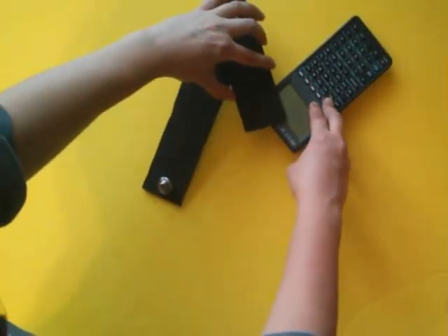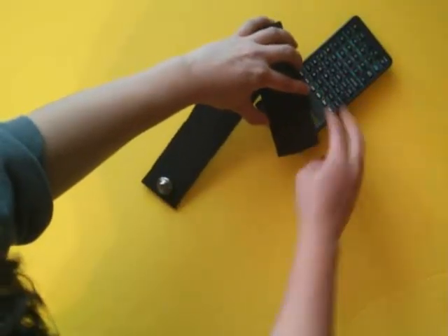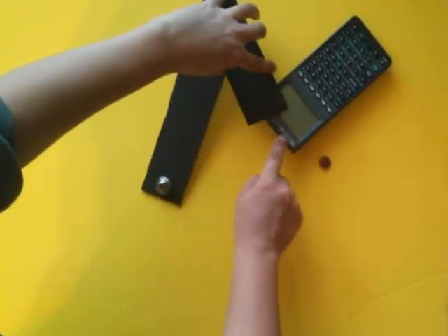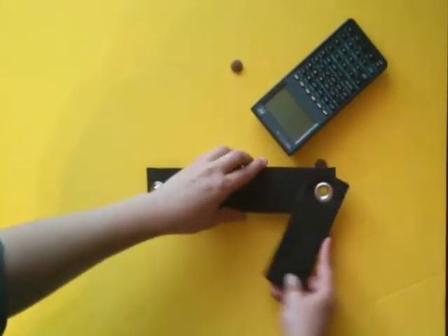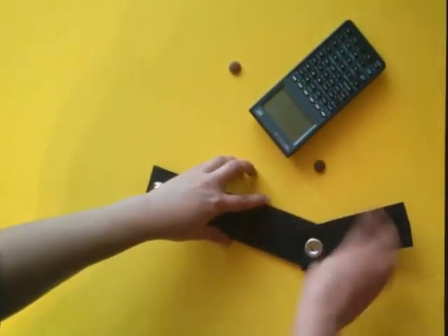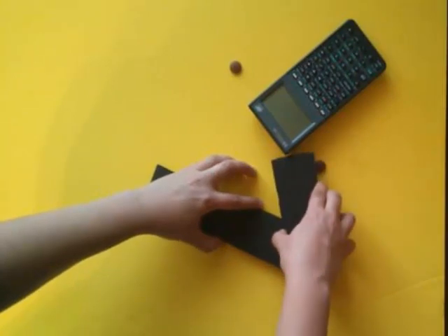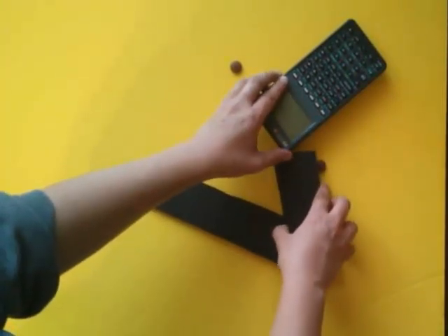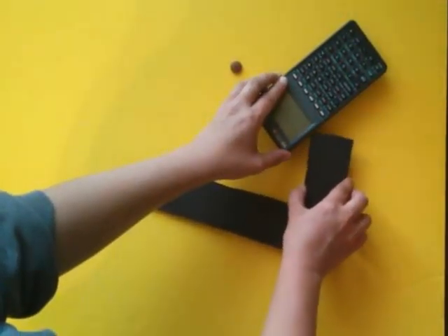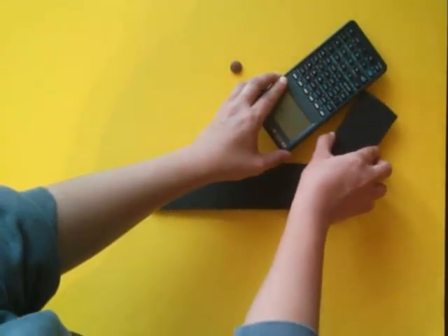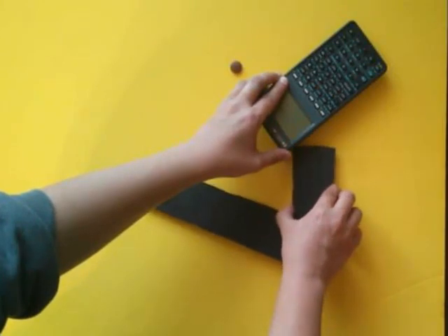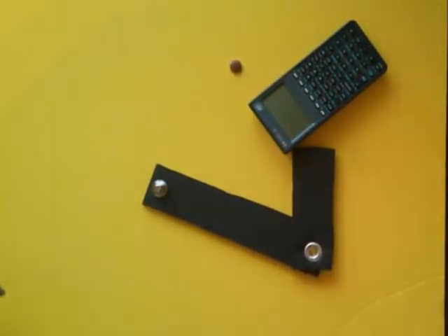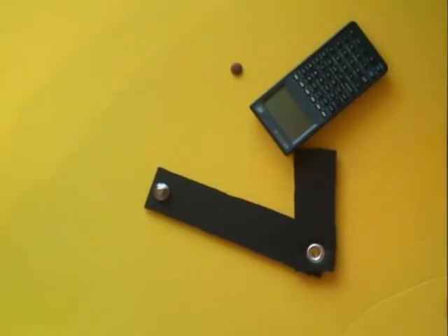So this is another example here where the end effector is touching the top edge of the obstacle, or on the bottom here where the end effector touches the edge of the obstacle down here. I'll find each of these theta 1, theta 2 coordinates and plot them on my configuration space, once again by using the inverse kinematics.